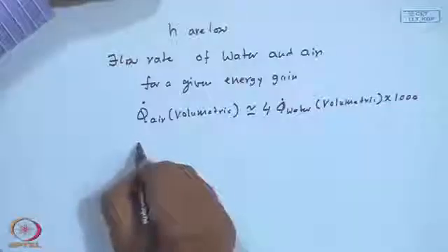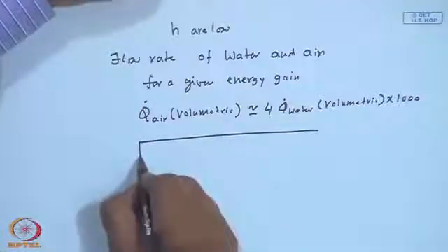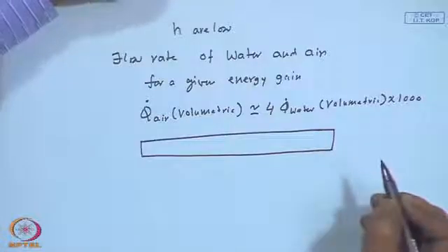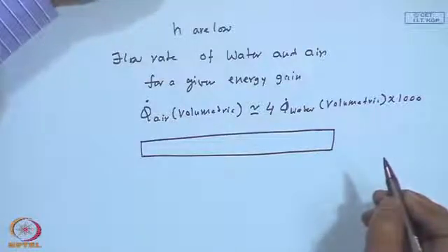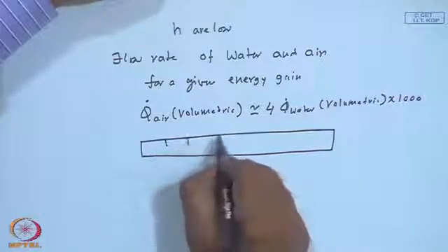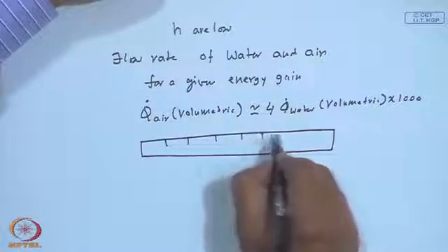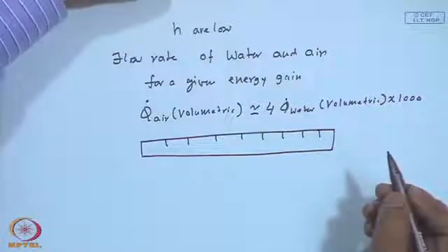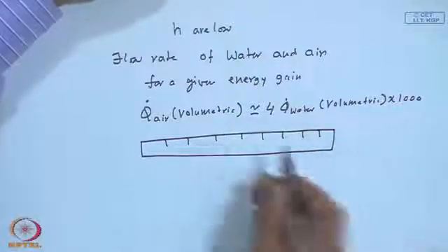So, that is one reason you do not have tubes in the case of air collectors; most of the time they are ducts. In the absence of a high heat transfer coefficient, there will be many techniques. Somebody may put fins or obstructions or turbulence breakers or flow breakers to enhance the heat transfer coefficient, but right now this is not our objective.